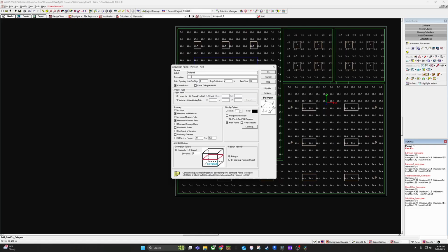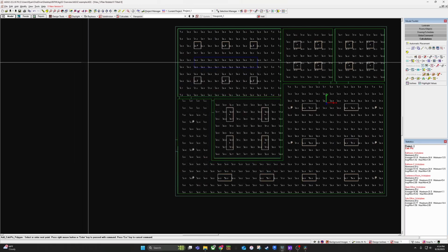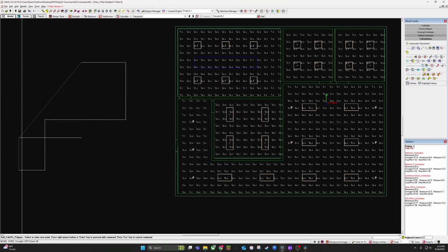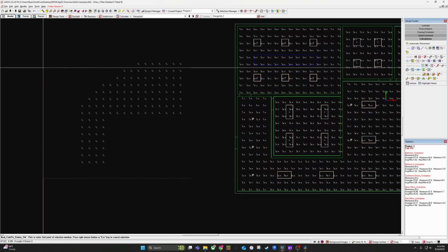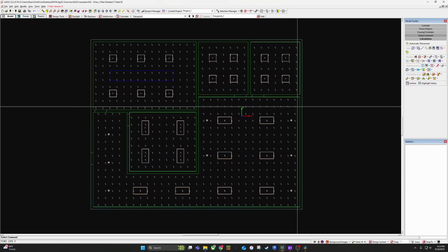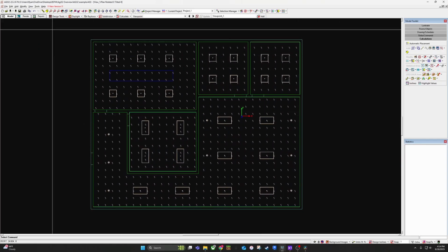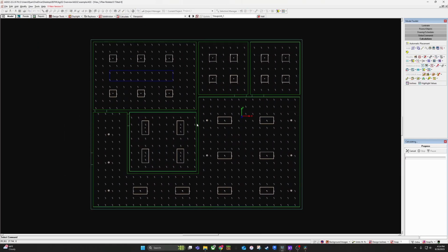Usually we have 2x2 foot spacing, and this shows the work plane height. Great. I guess you can just draw it out. Great. Just go and delete them. Calculate again. Whenever you delete calculation points, the whole thing resets because this is a great software.